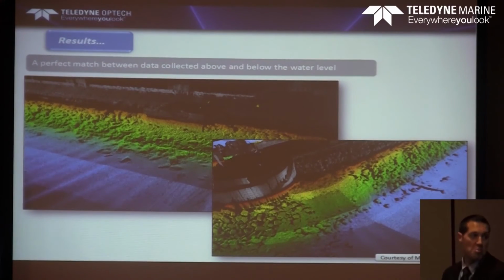Now I'm going to show you some images, but the result is really nice. You get a seamless integration between the data sets. In this case, you can see the fine details of the multi-beam, and you get the data set from the laser scanner. Everything matched perfectly, and it's a really good tool, to be honest, also to check the quality of the two results, because whenever you have only one system, you have to trust that the geometry is perfect, so it's right. But if you have 2 systems with the same geometry, you're 100% sure that the result is correct.